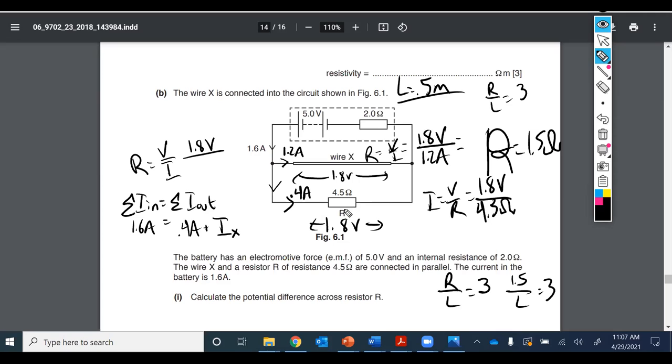Remember what resistors are. They're just pieces of metal that have certain resistivity. They have a certain length and a certain cross-sectional area, and it's those 3 things that really govern what the resistance is. So that there again is your resistivity equation, but this time solving it for R. We take a piece of wire, wrap it all up and put it in a little plastic capsule, and there's a resistor, but this wire itself acts as a resistor, stretched out like that.